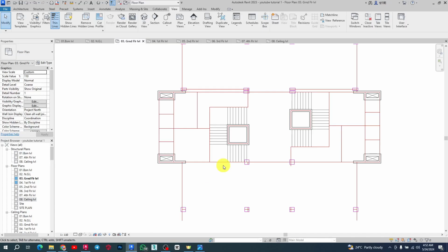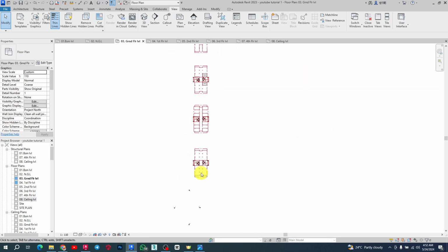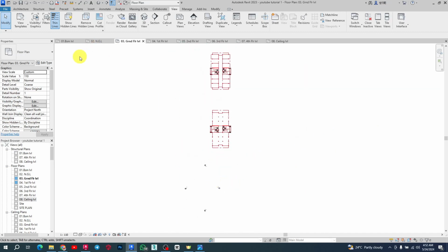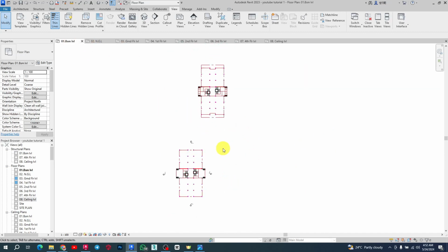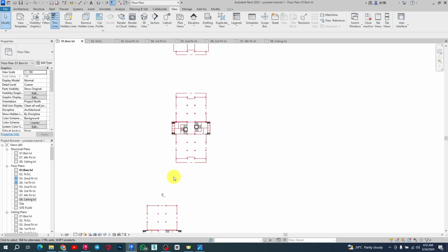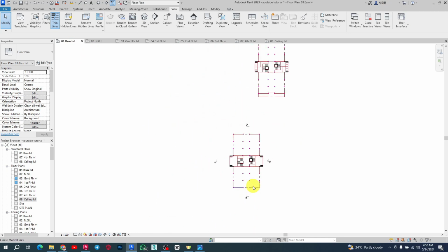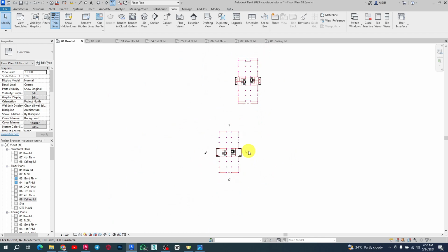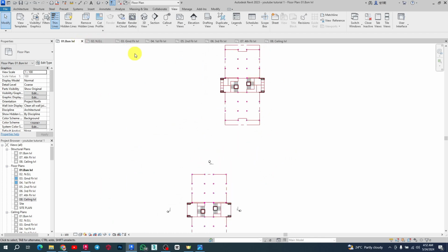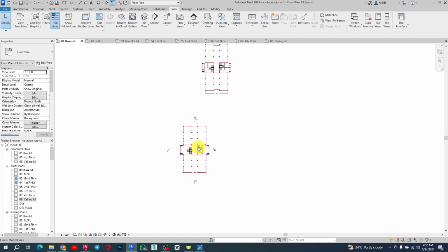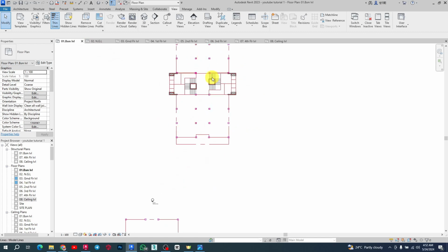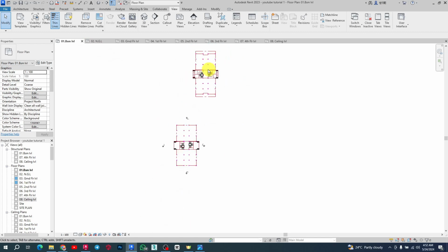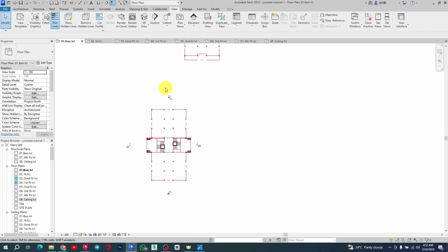Back in Revit now, we had our drawing existing here. This is where we ended. We imported the drawing, and then we're about to position it on the different levels, the levels that we designed them for. So this is our basement here, and this is the ground floor. I'm going to be placing them at the different levels that we have defined.